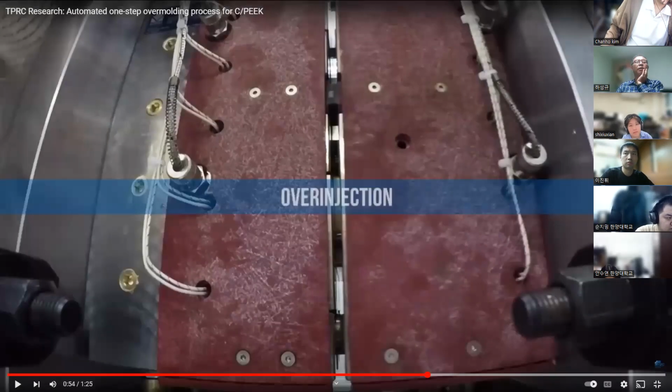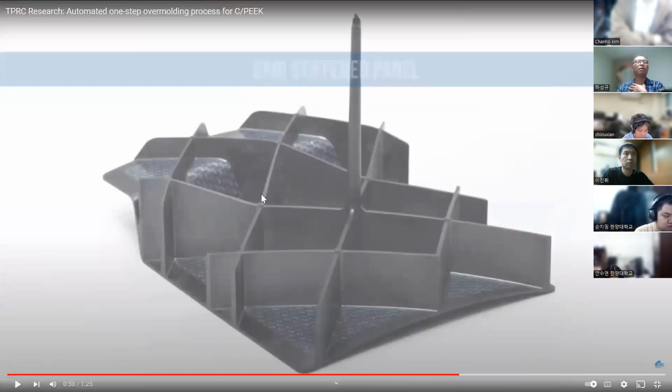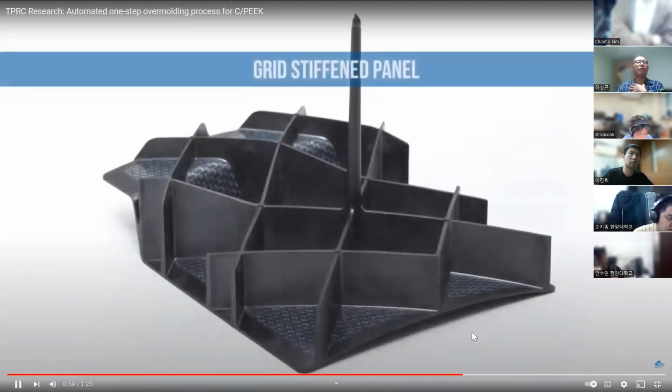Now, this is a very important manufacturing procedure. We insert the flat plate with a certain shape. Now, during the consolidation, we can do over injection. What does it mean, over injection? We can inject some plastic to have these very complicated structures. So this rib, let's just call it the rib, or some reinforced structures, can be overmolded as just one piece with the main structures. And this structure can be so strong,